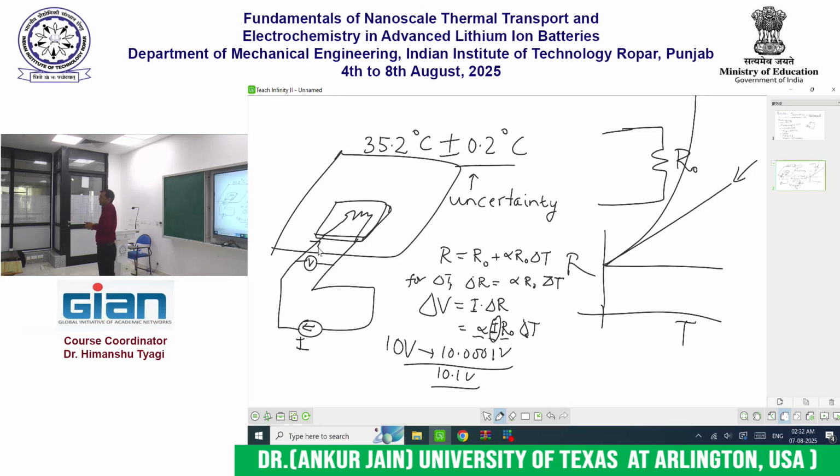Generally, in resistors, when temperature becomes high, then the resistance properties are lost. Sure. So I'm not sending a ton of current, right? I'm not sending an unrealistically large amount of current. But nevertheless, at large currents, this resistor will generate its own heat. And so the local temperature that I want to measure here will get affected by the sensor itself.